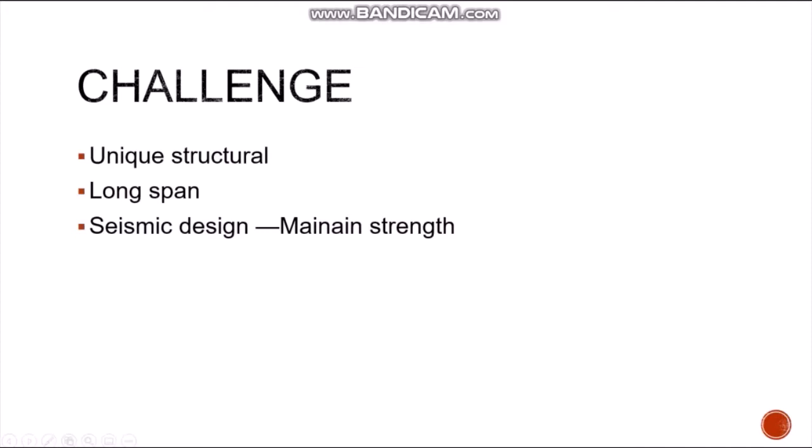Ductile detailing measures for the bracing members in special concentrically braced frames were thus insufficient to prevent collapse of the roof. It was necessary to limit the post-buckling axial shortening of the top chords and the compression diagonals of the primary trusses, thereby limiting degradation of compressive strength.